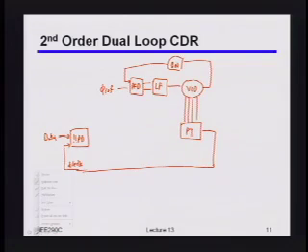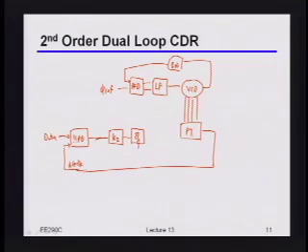But now, as we said, instead of making this loop filter only have one integration in it, I'm actually going to have two integrations. Okay, so let's draw what that would look like. For reasons that will hopefully become apparent in a second, let's say I put some gain, then I accumulate the thing once, I accumulate it again, and then I feed it to my phase interpolator.